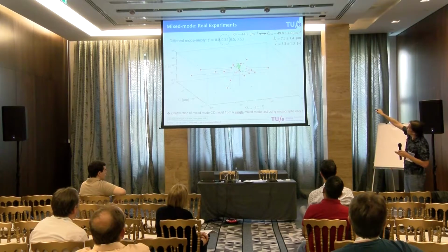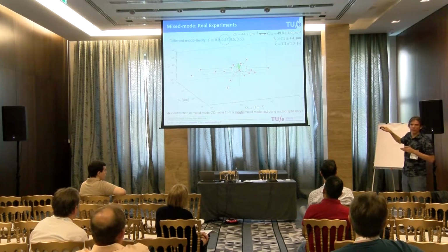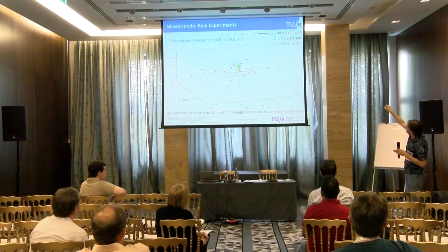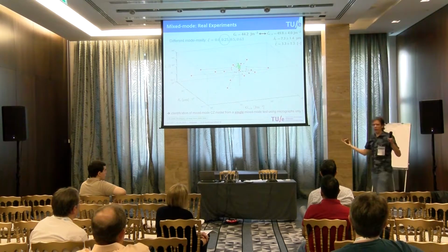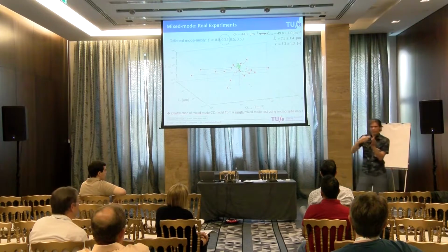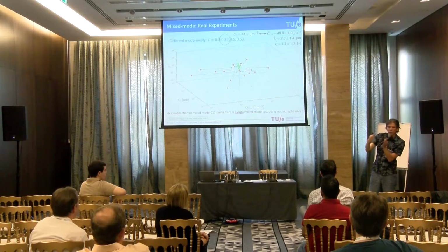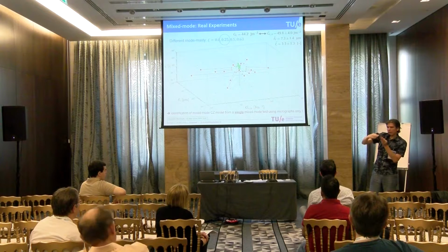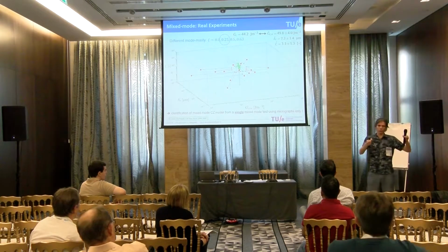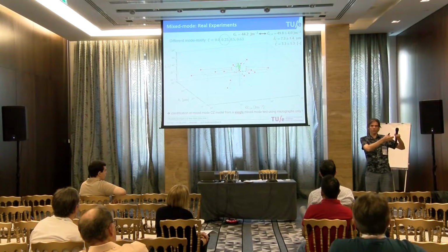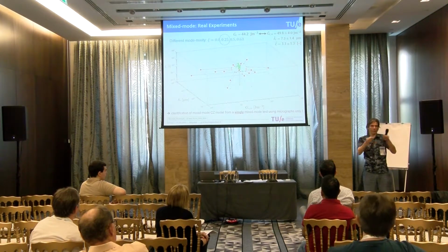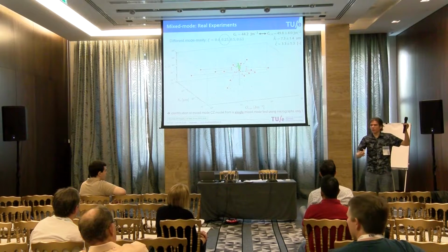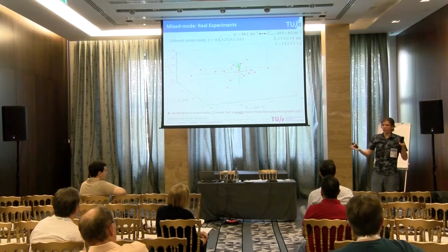The first one you get from the mode 1 test, and this agrees with the experimental uncertainty. The second one is very hard to know, but we use this model system with a glue layer, and a critical displacement of something like 7 micrometers corresponds to a failure displacement of something like 50 micrometers, or maybe somewhere between 30 and 100 micrometers, and that's what we see.